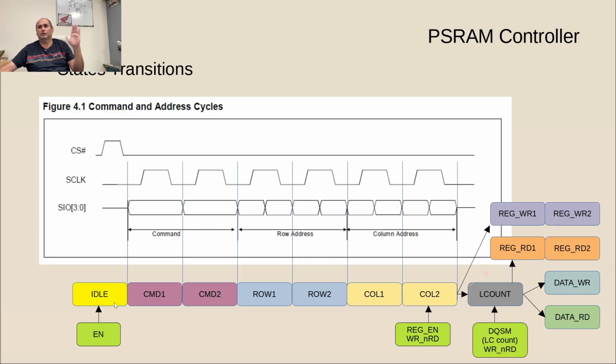So, first of all, everything triggers if there is an enable. We latch a new command, address, data, and all the other signals. If enable changes state from low to high, from 0 to 1, we know that we trigger the flow. So it will transition through those states, and it will go bang, bang, bang, bang, bang, bang.